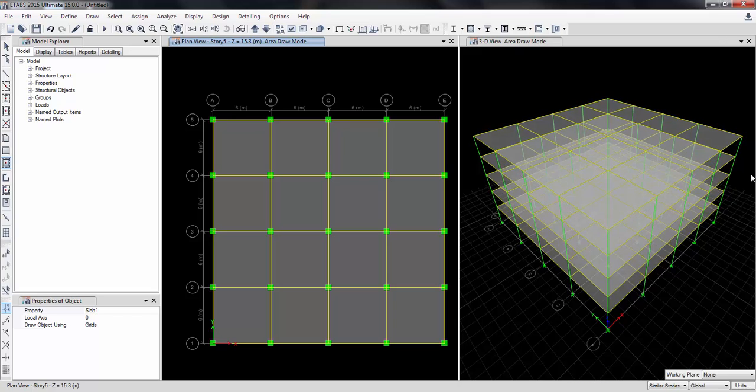the slab is drawn. So for doing any analysis purpose, we should keep these supports to be fixed, and for just doing design we should keep it as same pin jointed itself. The pin jointed is not really possible on the site.